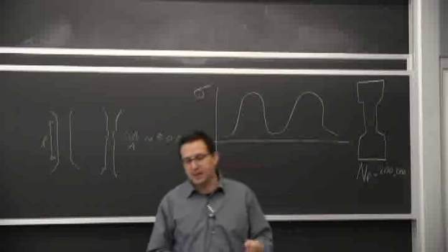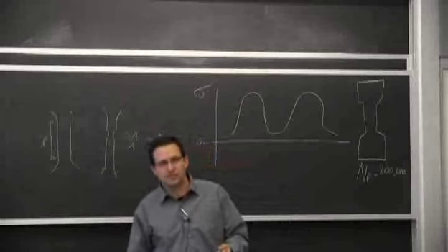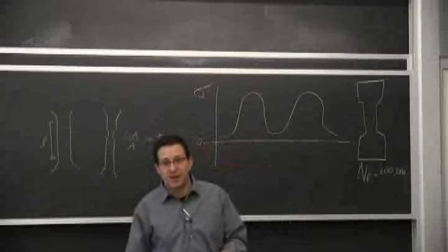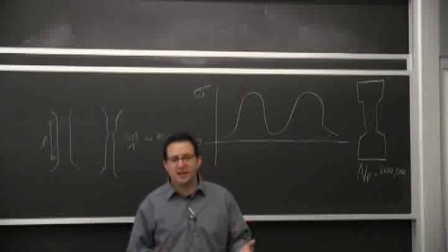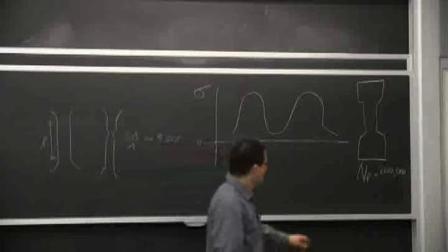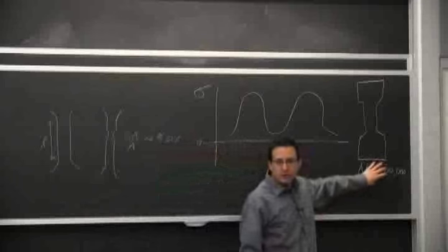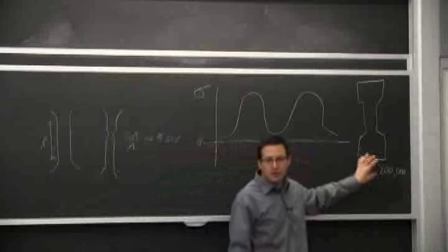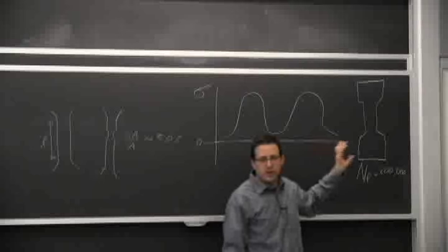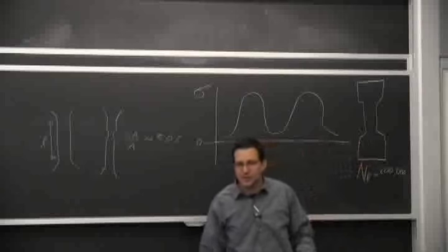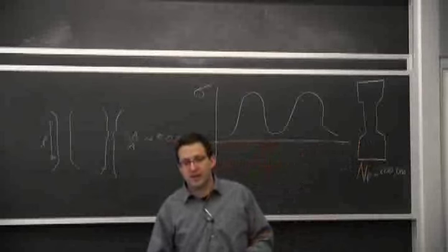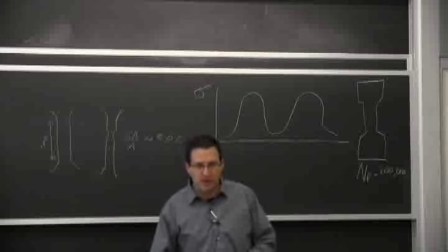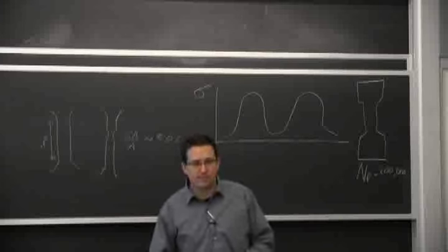But to some extent, it's a little bit like when we talked about the stress intensity factor. We don't necessarily need to know. If we run enough tests to have a range, we know that's the material property. For this loading, it will fail between 100,000 and 300,000 cycles, and we can design based on that. But we do have to run multiple tests because it will never fail exactly at the same time.